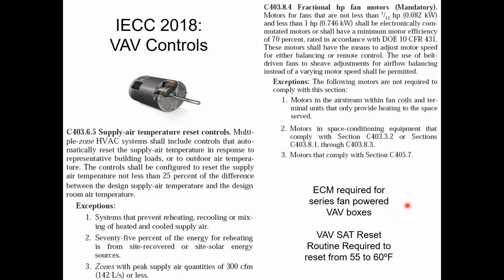Now, if you have a parallel box, you could still use a PSC blower if you wanted to, because in those cases, you'll be in the exception category of number 1 right here, where I'm only using the fan to provide heat to the space. So a parallel box does not have to have an ECM. A series box does have to have an ECM.